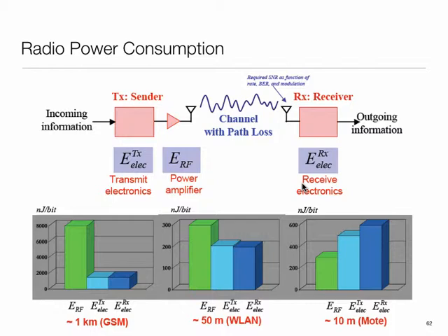The other thing is that, in response to our question, these radios tend to be more sophisticated. They have more sophisticated coding schemes, they have more sophisticated architectures, so they usually excel if I'm sending a lot of bits. Remember, I had mentioned earlier that for processors, an 8-bit microcontroller may have lower power, but it may take more energy to do a complicated job. Same thing out here. So this nanojoules per bit is not the whole story, okay? And we'll see that.